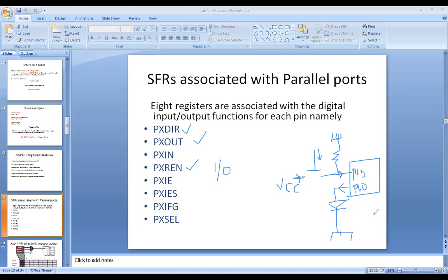So now when the switch is off, when you pull your hand back, what P1.3 reads is 0 because of this ground. And when the switch is on, P1.3 becomes logic 1. And this transition you see only when the switch is on. So whatever we want to do when the switch is off, we will do. When the switch is on, whatever you want to change, we will change it in the program.